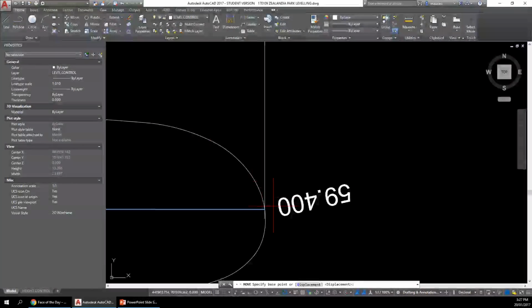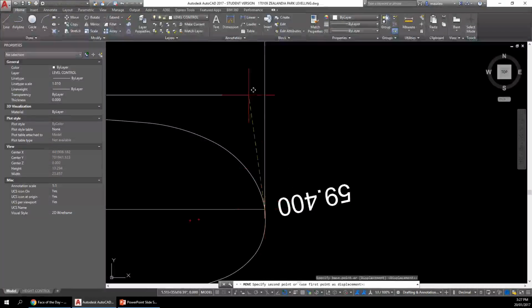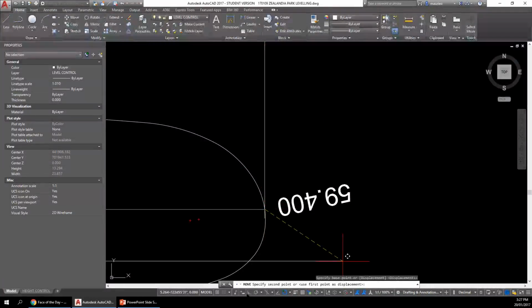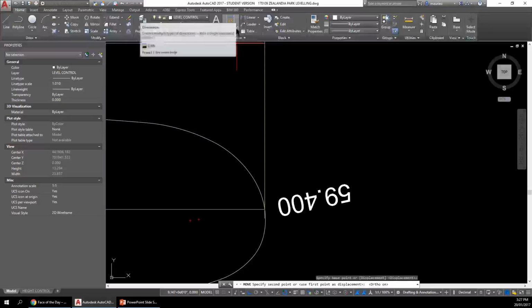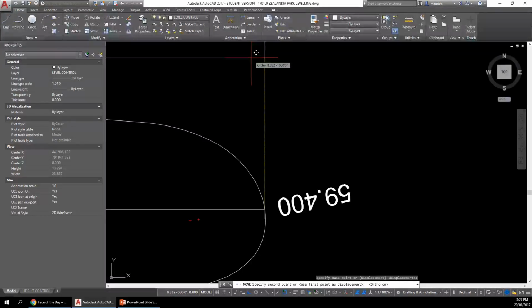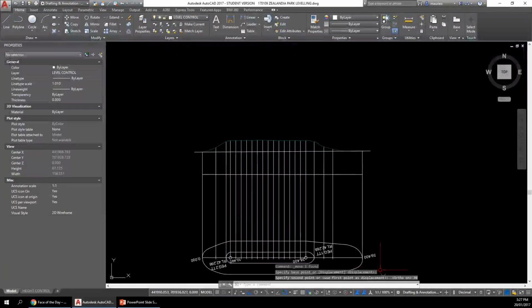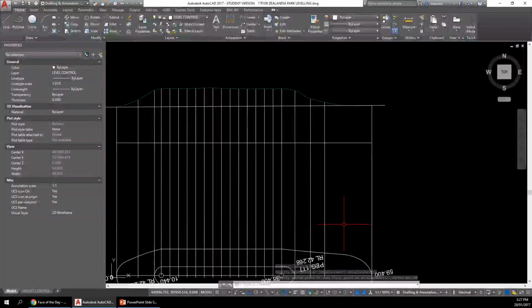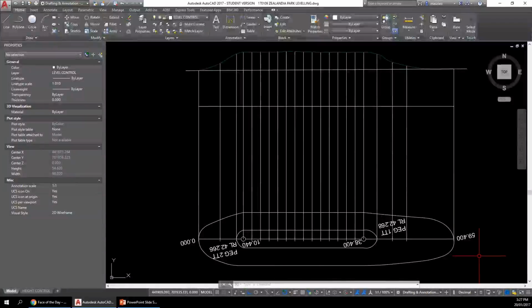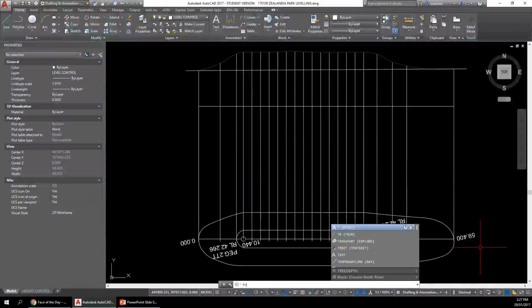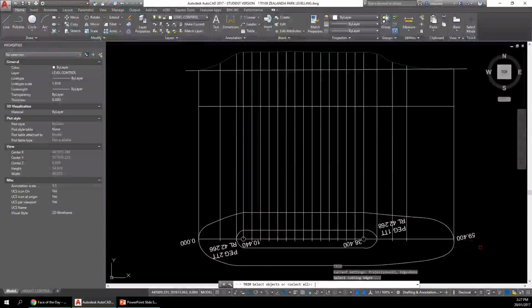and I'll just turn on the ortho on the end, and we'll just go up there 30. Okay, and that should put that line up there 30, and it should have moved it. So that's it there. Now we'll just trim to that line. Now that's what we call the height above datum, so that'll be at 30.